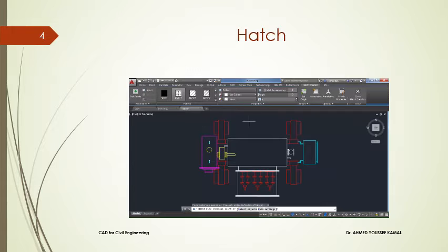So right now let's say that I want to create a hatch in this area. When you move your cursor to this area, you'll see a preview of the hatch. You may or may not need this kind of hatch, but let's just click it. When you click here, you'll see that the hatch automatically detects the island and fills the complete island, excluding this extra geometry.